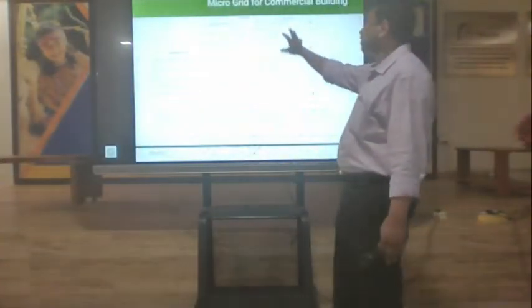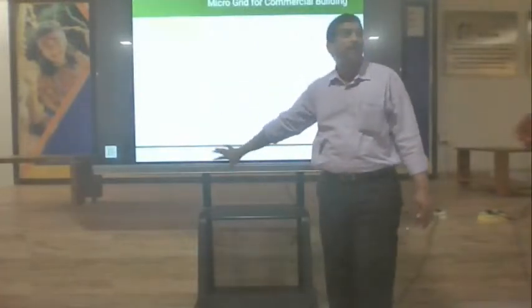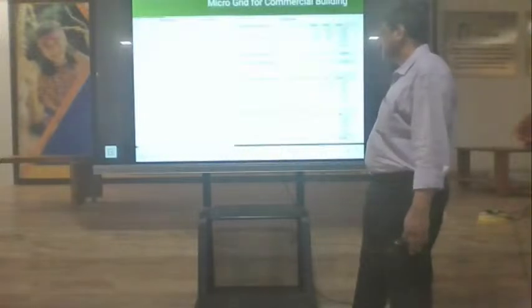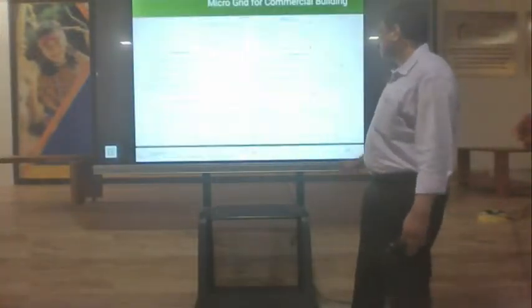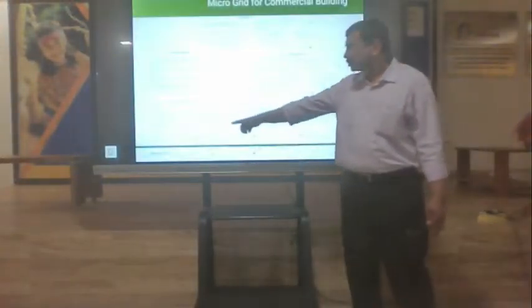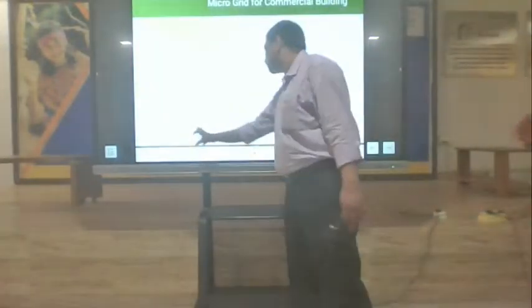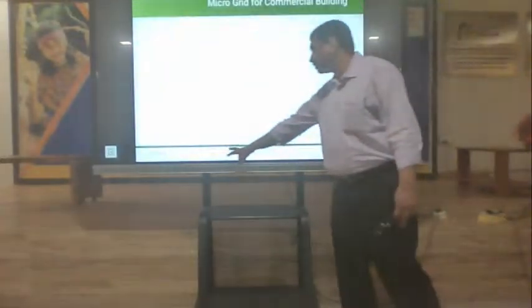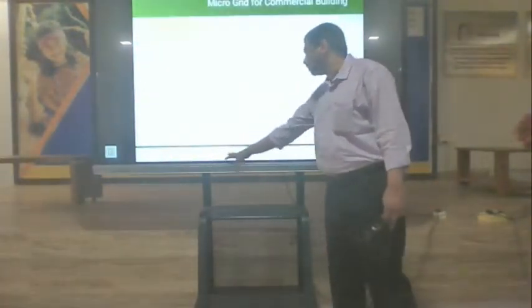In case power is not there, and solar is not there, we have a battery backup. So again we have a battery network, a set of batteries, a 230 volts battery bank. We have a DC-DC converter from 230 volts to 12 volts to charge each battery. We have a series of around 17 batteries. These are all connected in parallel, and we have got a DC bus.